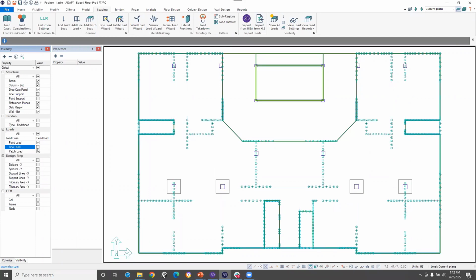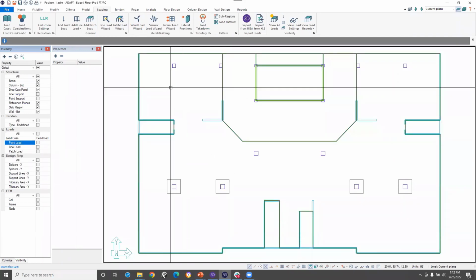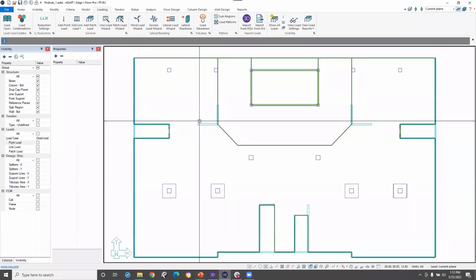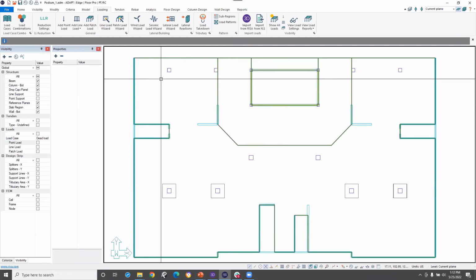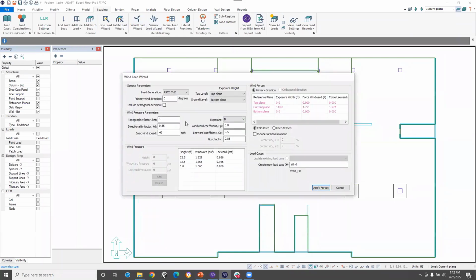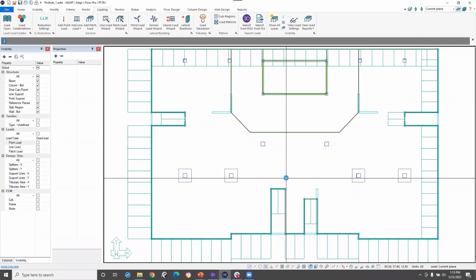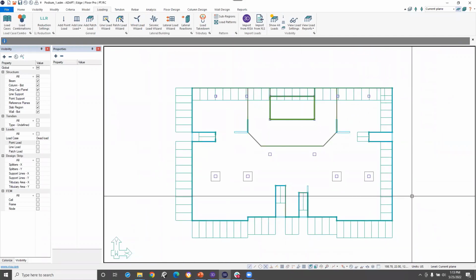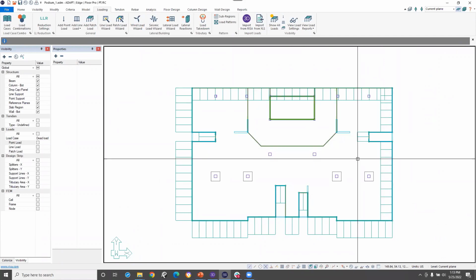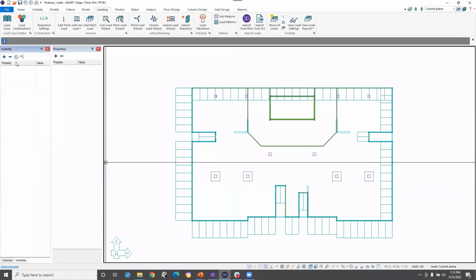Awesome. Let's go ahead and turn off some of our loading now. Really, I could go ahead and apply wind loads for my podium structure using the built-in wind load wizard, right? Alan went ahead and said we're using 144. Well, that's wrong. I don't put that there. I want my wind in the 0 degree and include the orthogonal, for example, and the wind speed. I want 144. We can go ahead and apply these forces, right? We have windward, leeward forces for both the X and Y direction. So pretty straightforward. We'll go ahead and turn those off as well.